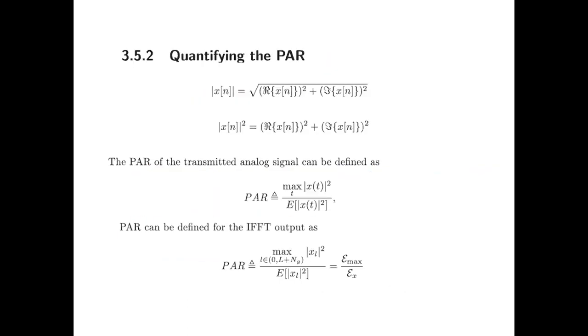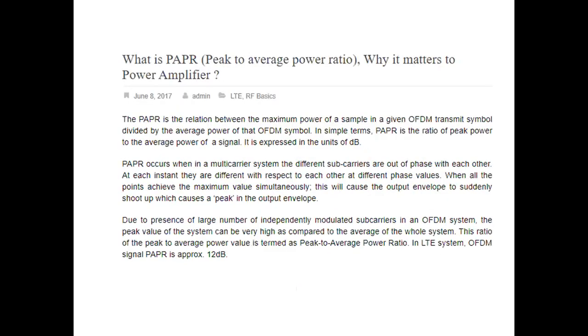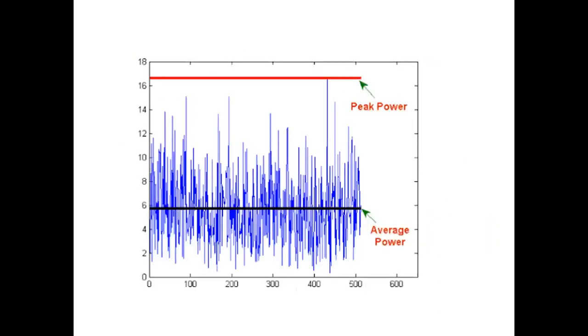And you can see here the formula for the peak to average ratio is given by the maximum power divided by the average power, right? The maximum divided by the average power. And a logical solution to this, as we concluded in the previous class, would be to clip them off, right? That was one of the several methods. We are not going deep into it. Clipping is a very trivial method where you simply clip them off.